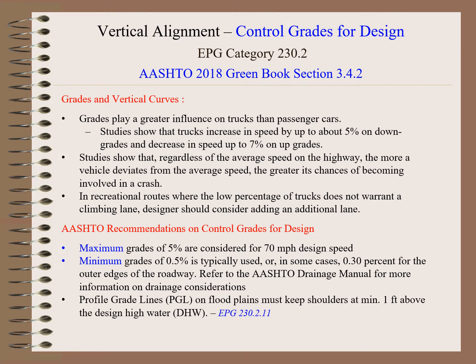Profile grade lines, or PGLs, on floodplains must keep shoulders at a minimum 1 foot above the design high water. That's found in EPG 230.2.11.